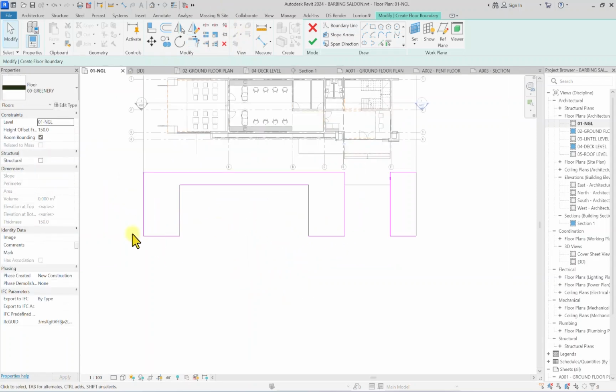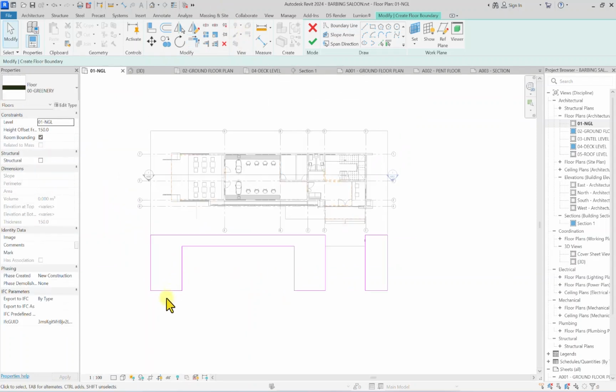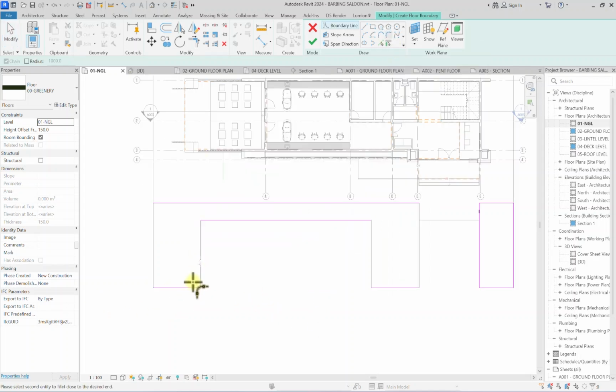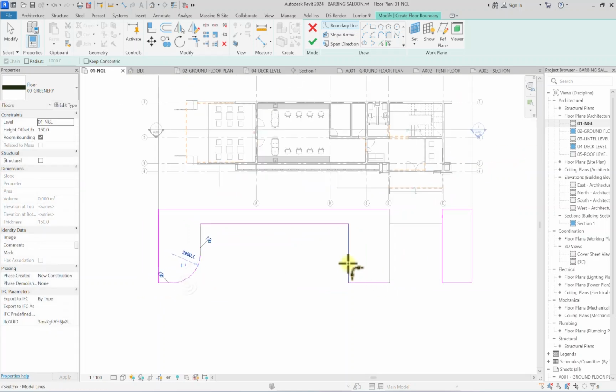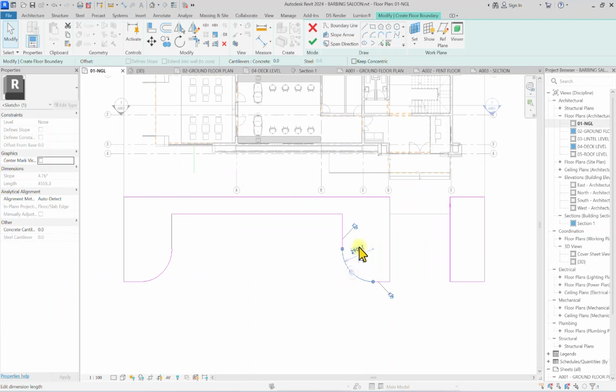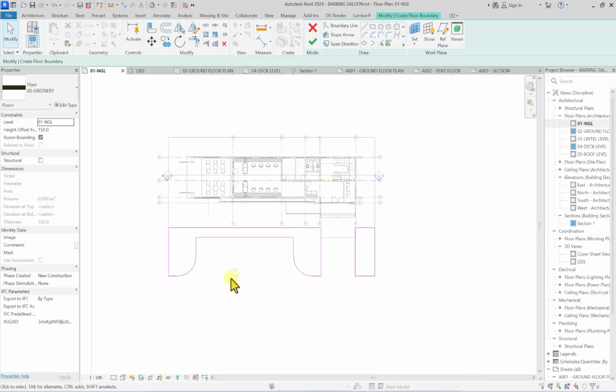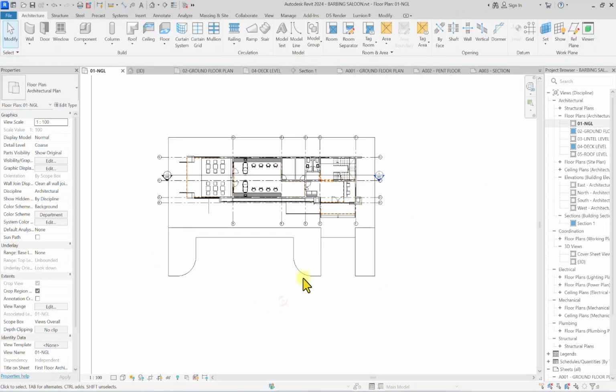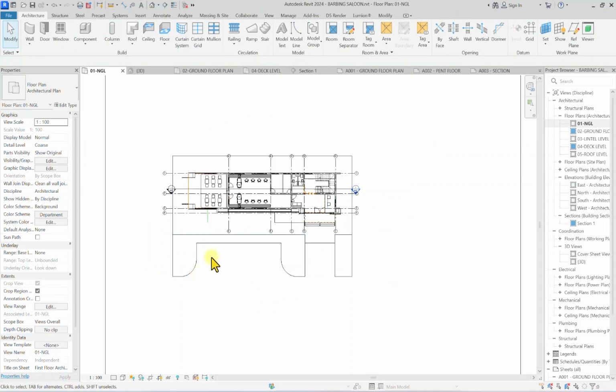Then I'm not going to, because there is something we call turning radius, which is very important. So we're just going to click on this turning radius where cars are using this fillet tool. And we're just going to create a turning radius of 3 meters here. Select this here. So after we have placed this, we're just going to click on this and change this to 3,000. So after doing this now, we are going to click on finish. Okay. So this is going to be where cars are going to park.